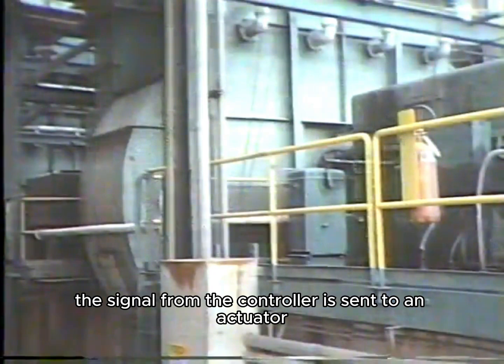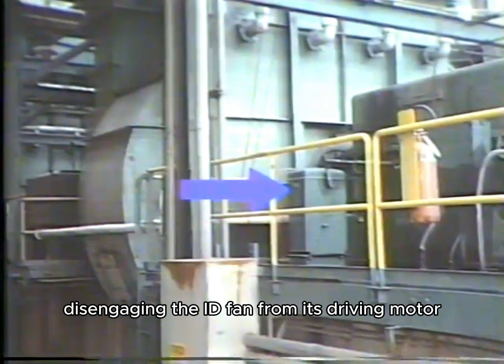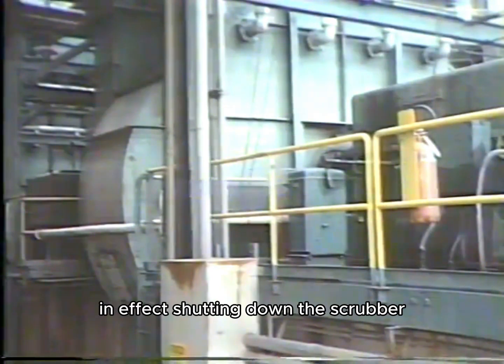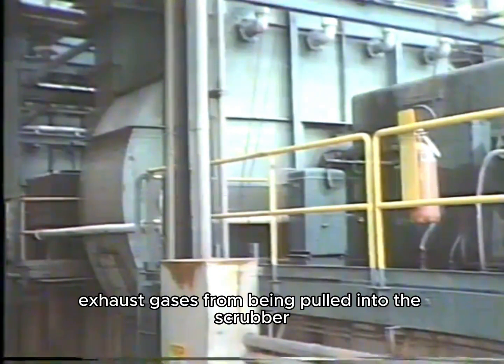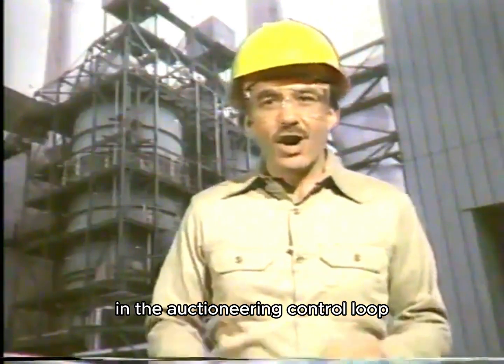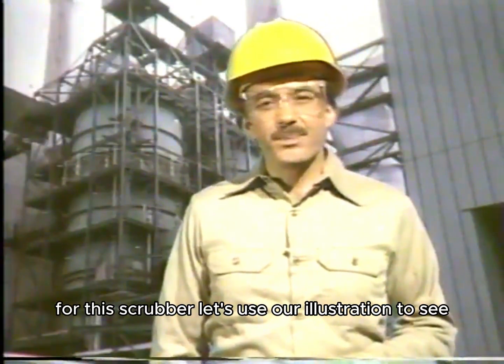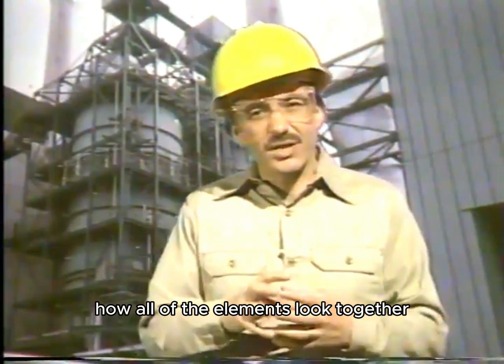The signal from the controller is sent to an actuator, which adjusts a hydraulic coupling disengaging the ID fan from its driving motor, in effect shutting down the scrubber and preventing any more hot furnace exhaust gases from being pulled into the scrubber. Okay, now that we've seen the instruments in the auctioneering control loop for this scrubber, let's use our illustration to see how all of the elements look together.